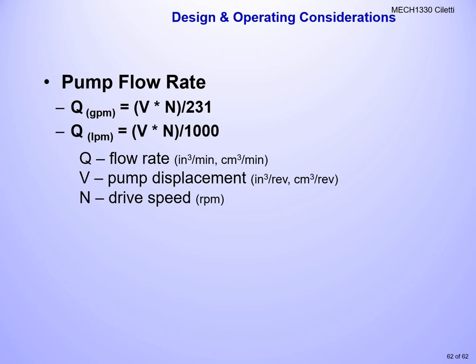We talked about gear pumps, piston pumps, screw pumps, vane pumps, all those different kinds of pumps and how they have a fixed or a varying volume that they can kick out. Remember, positive displacement pumps output a constant flow versus non-positive pumps that can output varying flow. That's the main concept, but know those main types of pumps. We talked about when we might use them based on their PSI, or if they're loud or things like that.